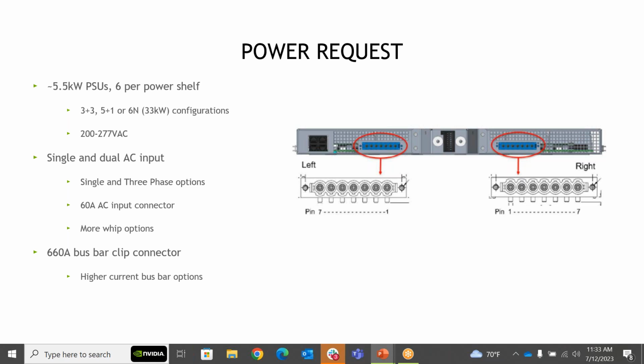And one more question. I think in one of the slides there was the input as single phase or three phase. So do you also foresee the power supply to go to a three phase, like a Vienna PFC, for example? Potentially as a future roadmap. At least in my personal experience, the true three-phase power supplies are still a little bit more expensive, and also the methodology that's been applied in ORV3 is very effective.